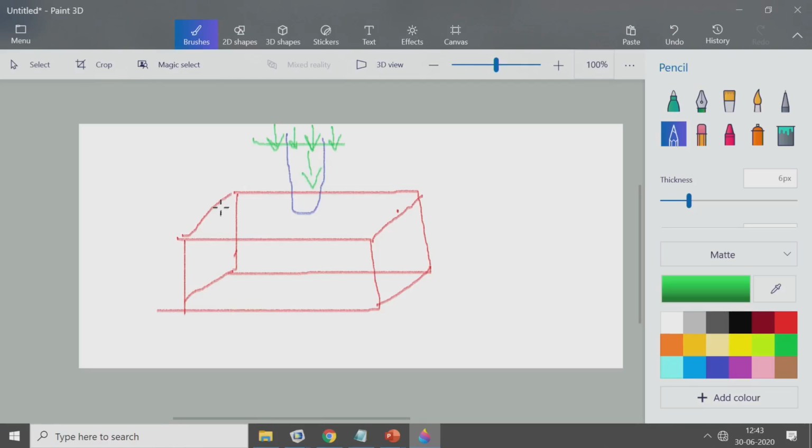So, for example, you have your probe over here, electrode probe over here. So, this will be hinged to some tissue, and this tissue will not be hanging somewhere, but it would be constrained somewhere. So, it needs to be given some kind of a fixed constraint. So, let us see how to apply the fixed constraint. What we are going to do is we are going to apply the fixed constraints on the walls, the side walls of your probe tissue, on the tissue. Okay. So, how do I do that?